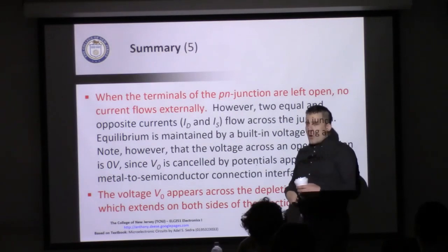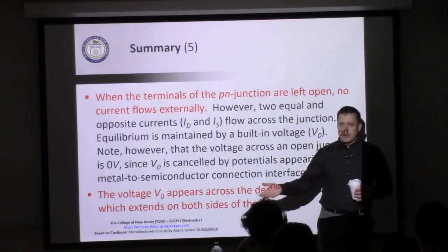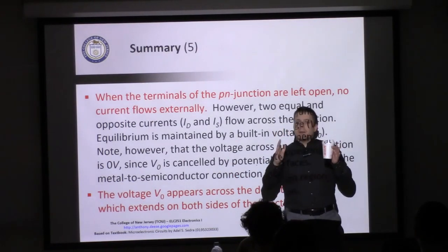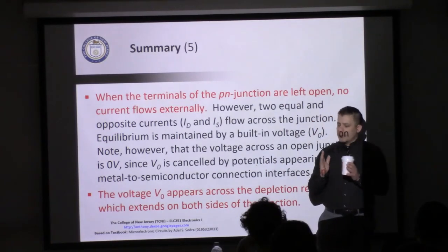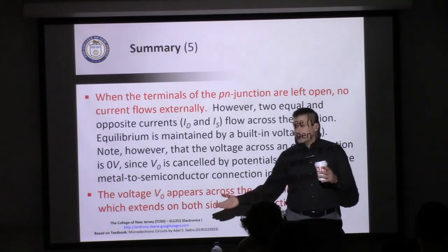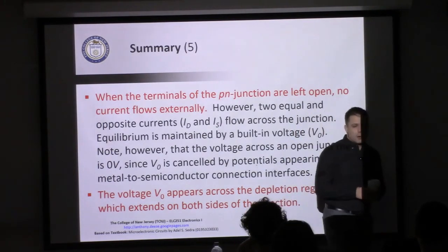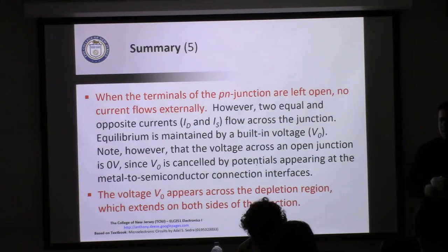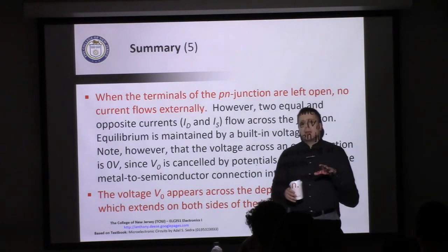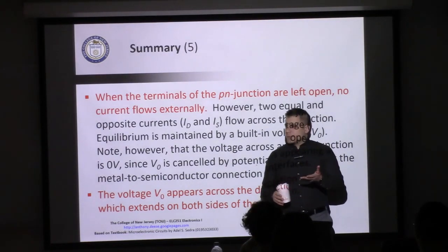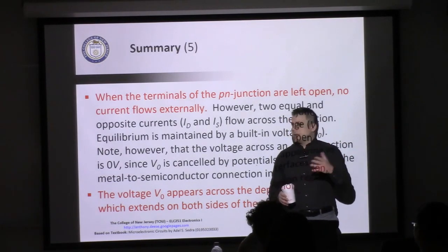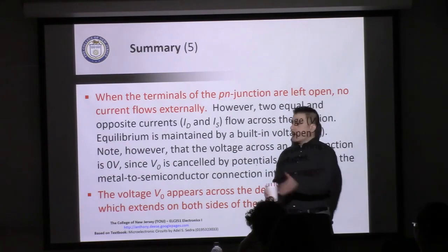So although we apply an external voltage and see a current flow, it's not a drift current that's flowing. The externally applied voltage reduces the barrier, or the width of the depletion region, allows diffusion to ramp up, and that's how we get our current flow. And then lastly, after we define a mathematical expression for that diffusion current, we end up with our exponential model, which is I equals IS times e to the V over VT, minus 1. And you'll see that's going to lead us directly into Chapter 4.